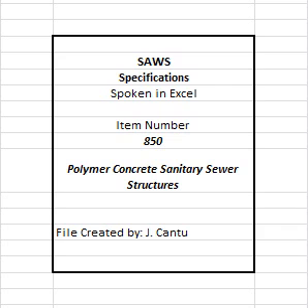16. Handling and shipping shall be performed in accordance with the manufacturer's instructions. 17. Installation. The installation of structures shall be in accordance with the project plans and specifications and the manufacturer's recommended practices. 18. Handling. Properly rated slings and spreader bar shall be used for lifting. 19. The type of rigging used shall be per the manufacturer's recommendation. 20. Sealing surfaces and joint components shall be inspected for damage and cleaned of all debris. 21. Apply joint lubricant to elastomeric seals. Use only lubricants approved by the manufacturer. 22. Use suitable equipment to handle and set structure. 23. Placement and compaction of surrounding backfill material shall be as per specification item number 804, Excavation, trenching, and backfill.